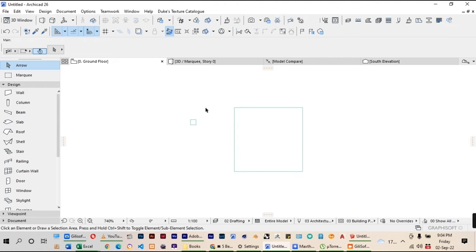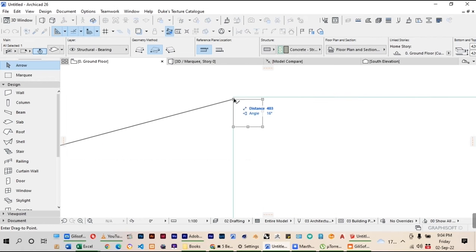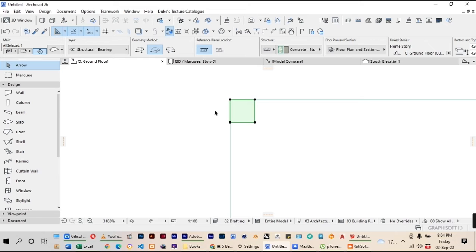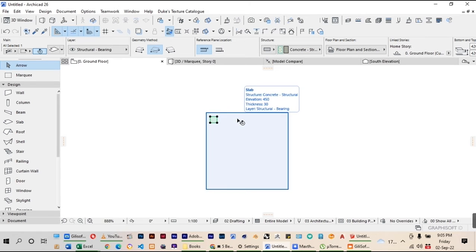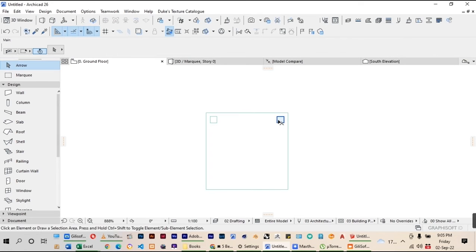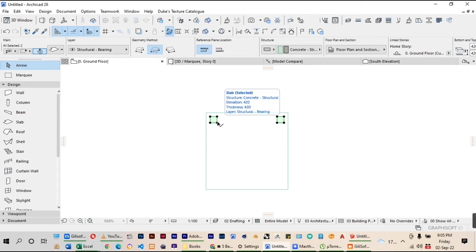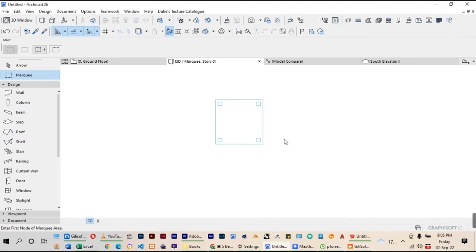That's it. Now it's a matter of positioning this one to the right place. We'll just deal with one first. The offset from the edges should be 30. So do 30 on this side and do an offset of 30 on the other side. One has already been done. Then we can mirror, that is Control M, copy, look for the center, enter, select these two, and then mirror a copy again. Then you can do a marquee of the same, right click, show marquee.